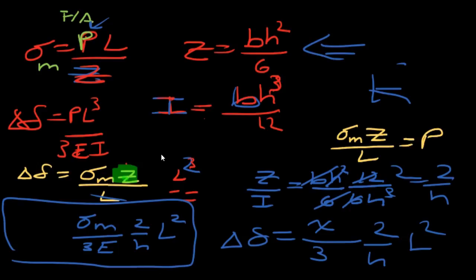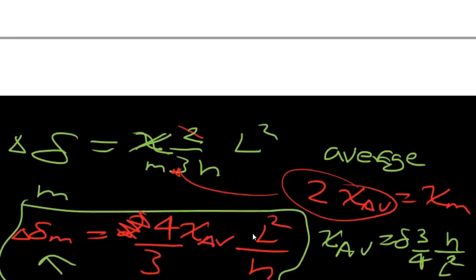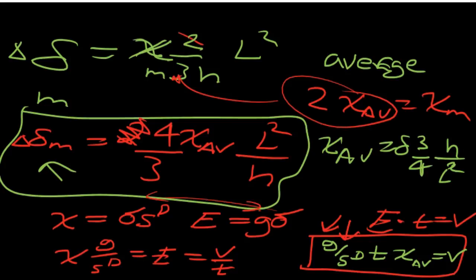So we developed a couple of equations. You can find that in the last video of this section, part 1. But essentially we got to the point where we related the maximum strain with the deflection, as seen in this equation, and also the deflection related to the maximum stress as well. And then we derived, using the average strain, which would be half, the voltage to be equal to the thickness multiplied by the piezoelectric g constant g31 and the s coefficient s11 D.